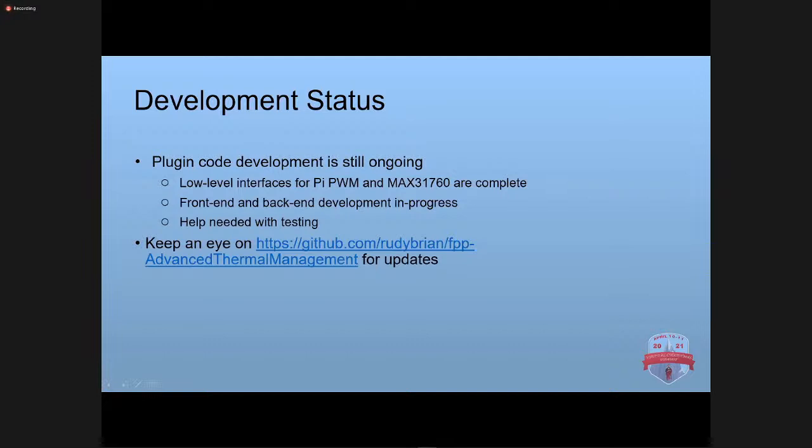A couple more posts in chat. Somebody says they have an ESP01 and ESP Home to manage fans and temperature in their boxes, using it with Home Assistant. Yes, so you could do that as well. If you have open GPIOs on the ESP01, you can do that separately from this. But you could potentially use one of the available GPIOs on the ESP for that.